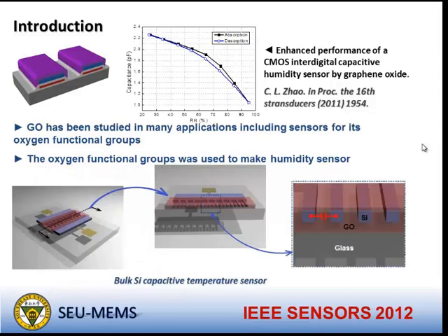So we designed a post-silicon temperature sensor that uses graphene oxide as a sensor material. The graphene oxide was used to fill the capacitor dielectrics. When the temperature increases, the dielectric constant increases exponentially, so the capacitance between the post-silicon electrodes can increase too.